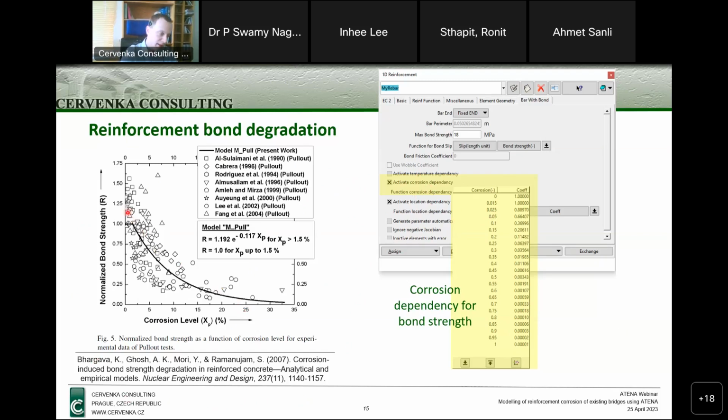that can be found in the literature, and came up with the following function, which firstly, up to some level, shows a plateau, because this phase is described by some minor swelling of the reinforcement, or minor buildup of the pressure around the reinforcement, and once this pressure exceeds the strength of the concrete, the microcracks form, and we can see the reduction.